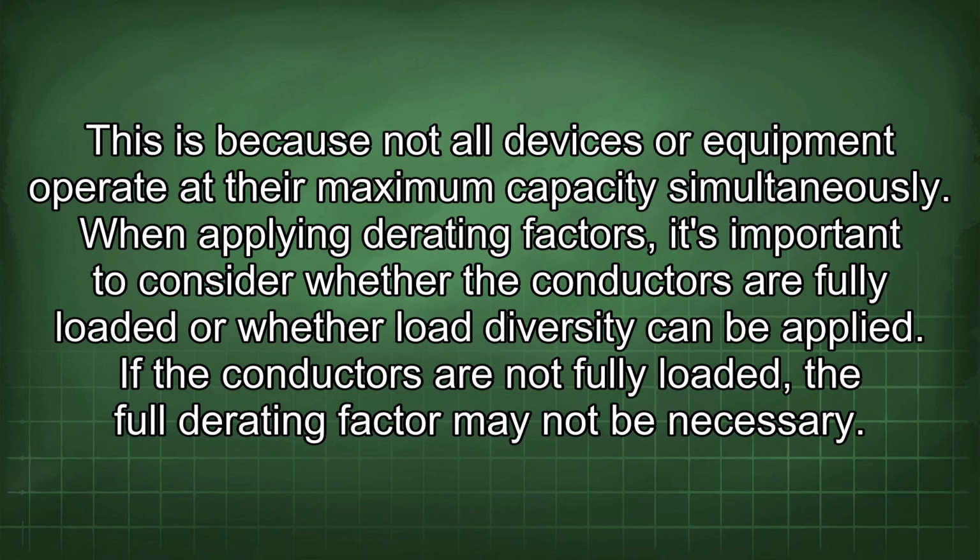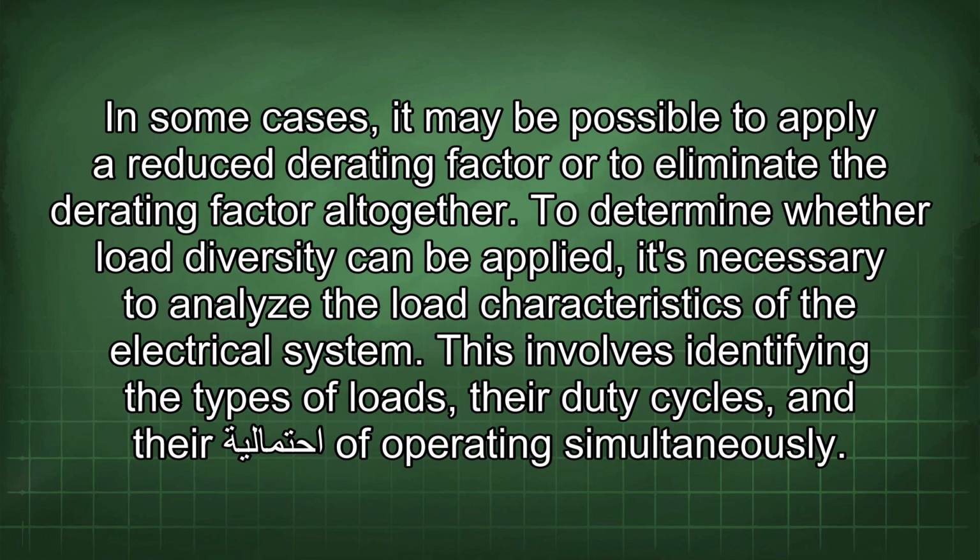When applying derating factors, it's important to consider whether the conductors are fully loaded or whether load diversity can be applied. If the conductors are not fully loaded, the full derating factor may not be necessary. In some cases, it may be possible to apply a reduced derating factor or to eliminate the derating factor altogether. To determine whether load diversity can be applied, it's necessary to analyze the load characteristics of the electrical system. This involves identifying the types of loads, the duty cycles, and the likelihood of operating simultaneously.